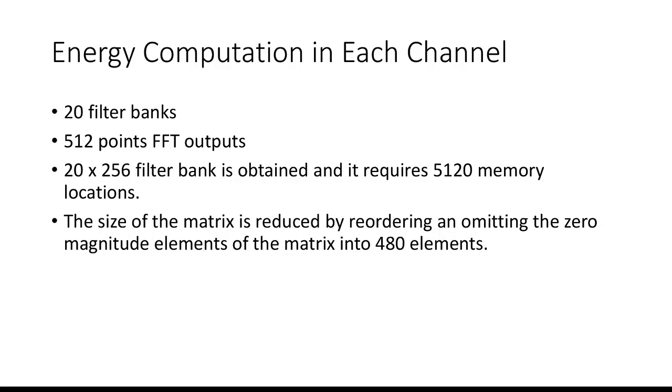A 20 by 256 filter bank is obtained and it requires 5120 memory locations. The size of the matrix is reduced by reordering and omitting the zero magnitude elements of the matrix into 480 elements.